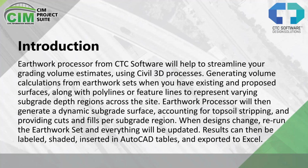Earthwork Processor will then generate dynamic subgrade surfaces and can account for topsoil stripping and provide cuts and fills per subgrade region. And when designs change, depths change, all we need to do is make an adjustment in Earthwork Processor and rerun it. And with those, we can export our results to an Excel. We can put those into our drawing as an AutoCAD table, and we can also label the region areas.